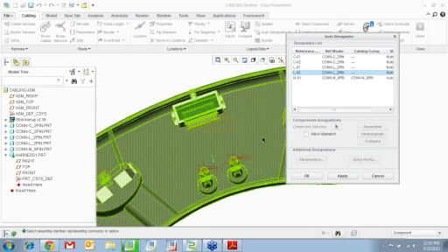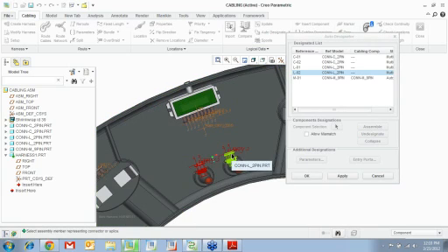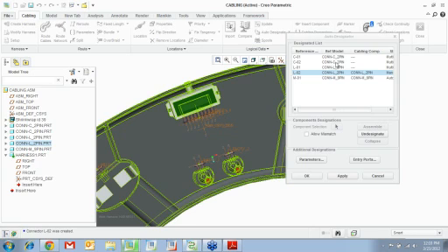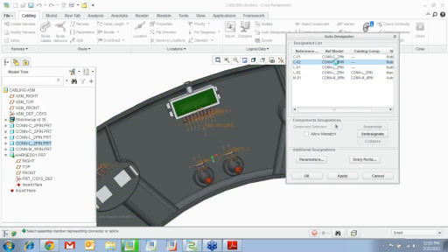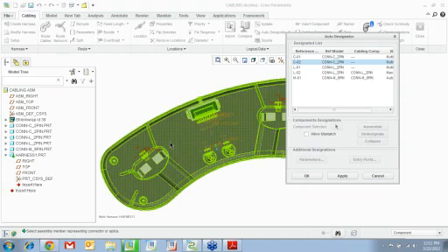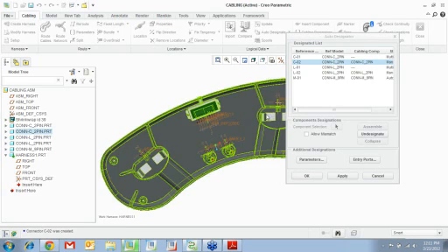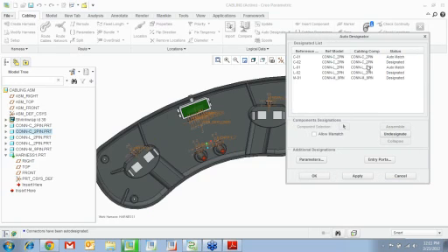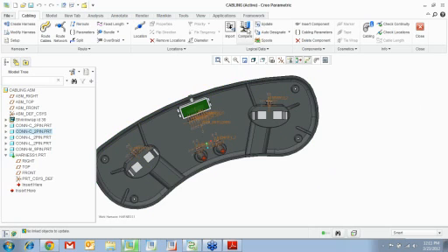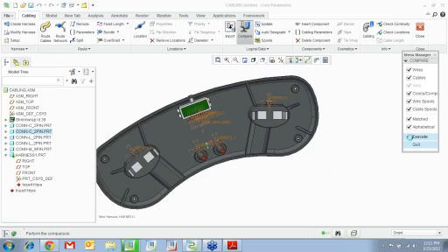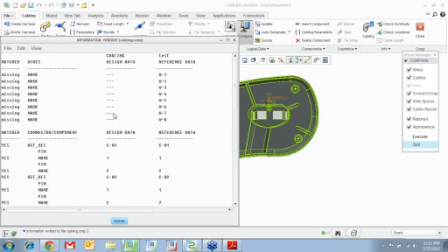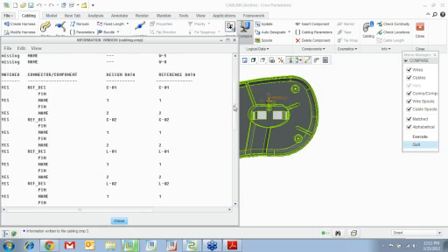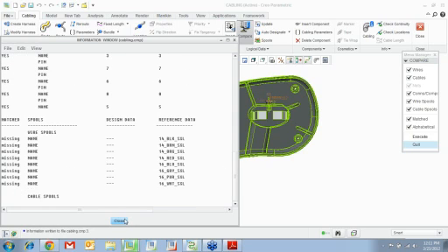So this part, number 2, is right here. Right? I picked one. You see there are 2 of them, 1 and 2. So I say this one's number 2. See that? And then you hit apply, you see it auto matches the other components. Now you say okay, you can go update it and do a comparison real quick just to see that. Notice the wires are not there, but everything else has been matched. Okay.